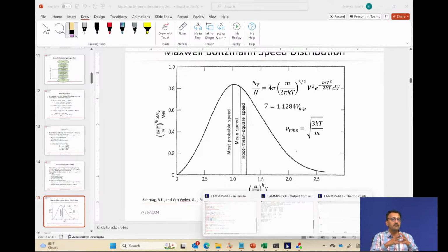One way, if you wanted to check this out, you can run this same calculation with a different random seed, and you might not see it happen. The second aspect is to reduce the time step. Instead of keeping it at 1 femtosecond, if you reduce it to 0.5 femtosecond, maybe that will take care of it and you won't have either a temperature spike or a drop. But either way, it is corrected. In equilibration, all you care about is that at the end of the run, you have a stable temperature, which was achieved. So I wouldn't be worried.